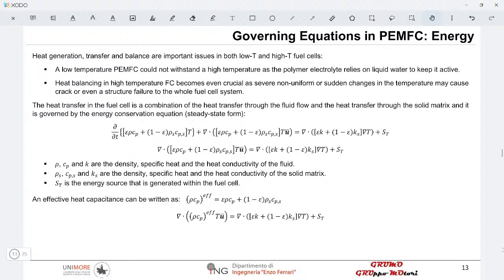Okay, that's valid in general, but where is that happening? It's happening at the catalyst layers. So that large amount of heat is dissipated in extremely small and thin components. So the local generation of heat will be extremely high. Okay, so the distribution of heat on the parts composing a fuel cell is very important for the local distribution of heat.